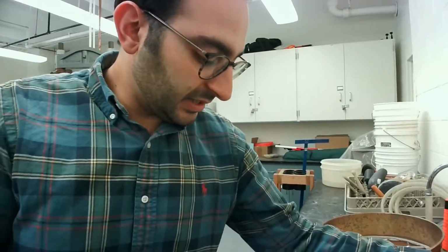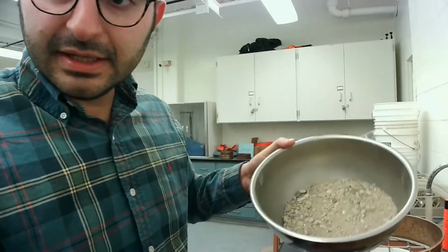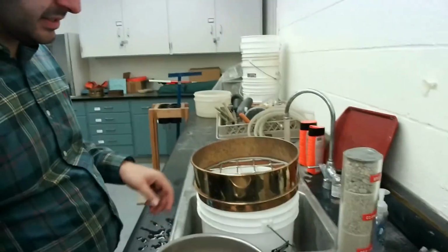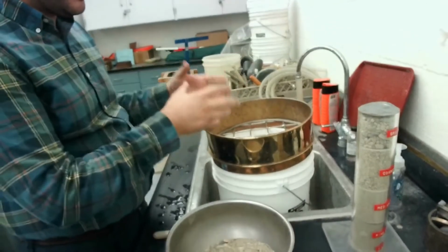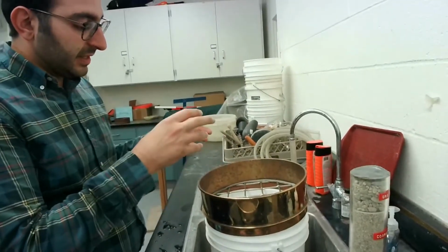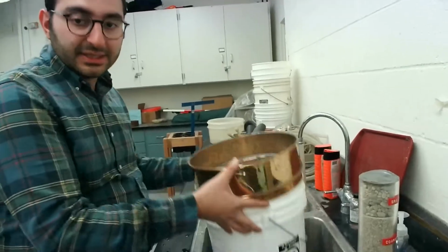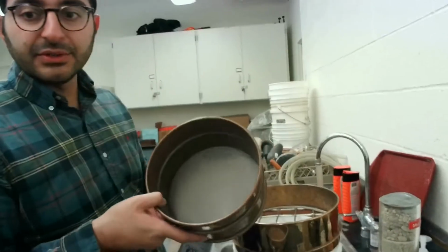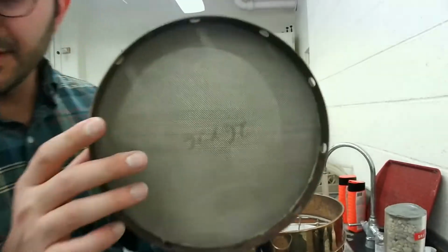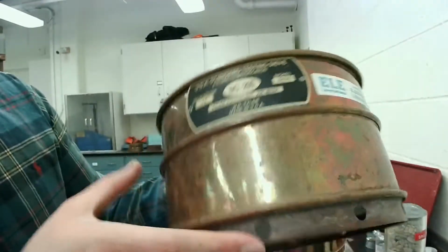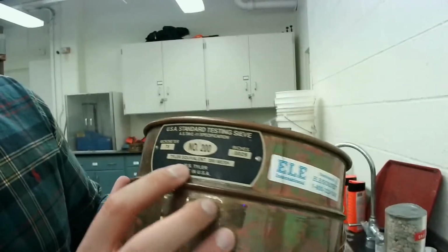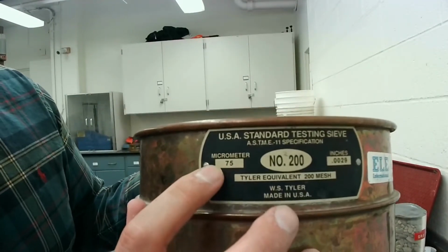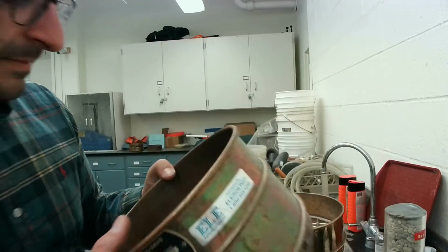So my idea here is to grab portions of this soil and then wash it. And basically what I'll do is grab the fines parts with water. They will all go, I'll be collecting them into this bucket that you're seeing here, right? And this is my number 200 sieve, right? This is a very, very fine sieve that you're seeing. So the designation is right here, number 200. And the size of the opening is 75 micrometers.